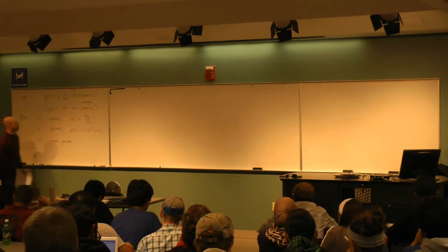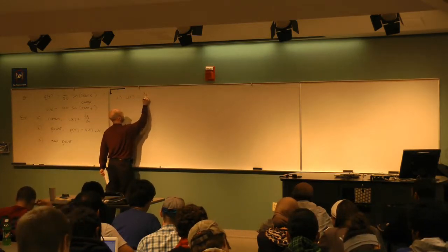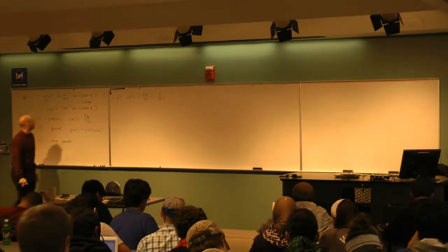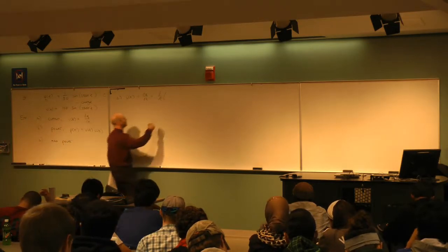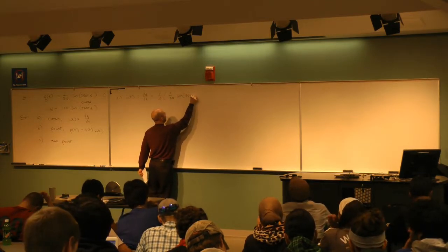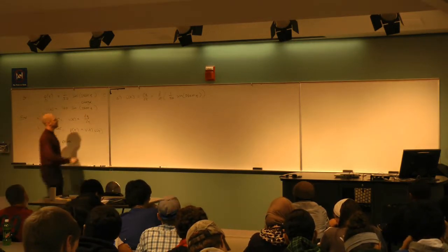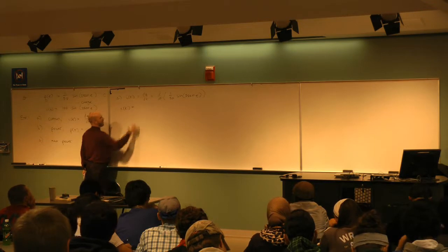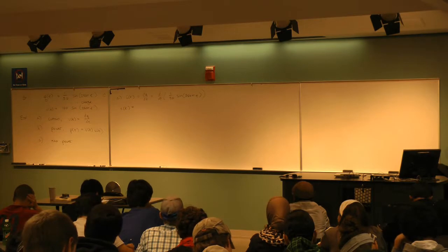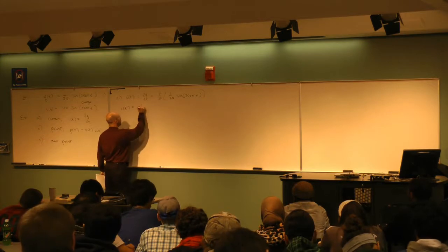All right, so first of all, the current, part A. I of t is the derivative dq/dt, so I'm going to take the derivative with respect to time of the charge function: 1 over 50 times the sine of 250 pi times t. So help me out. What do I do with the 1 over 50 out in front? It stays there, right? I've got a constant times a function. The constant stays out front. So I've got 1 over 50.